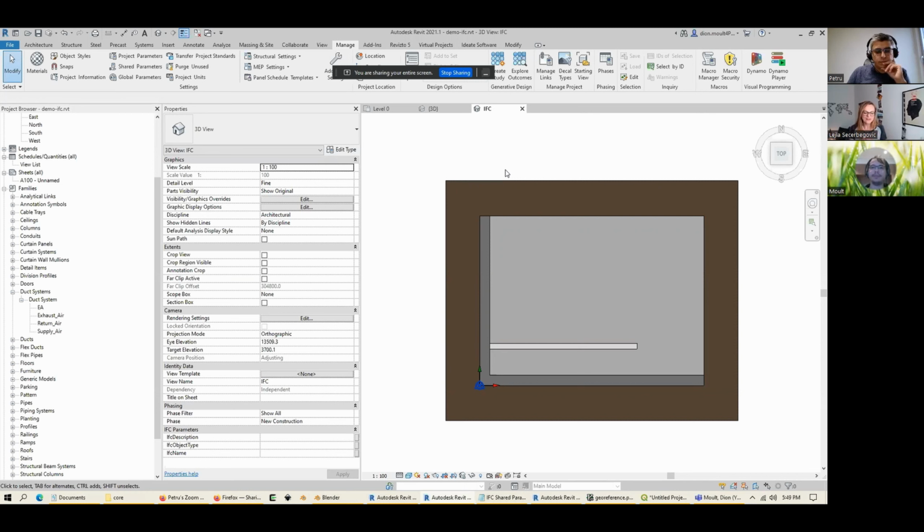Maybe just to add one thing, it's not like our decision not to focus on the Design Transfer View. I do understand that the concept behind the Design Transfer View is a lot smarter in certain points, but it's also not being certified or actively developed at the moment by buildingSMART. So all the software vendors are currently forced to work on the model view definitions which are currently certified, and that's the reference view. And for IFC 4.3, I guess there will be new ones, so the certification won't happen that soon for IFC 4.3. Yeah, that makes absolute sense.